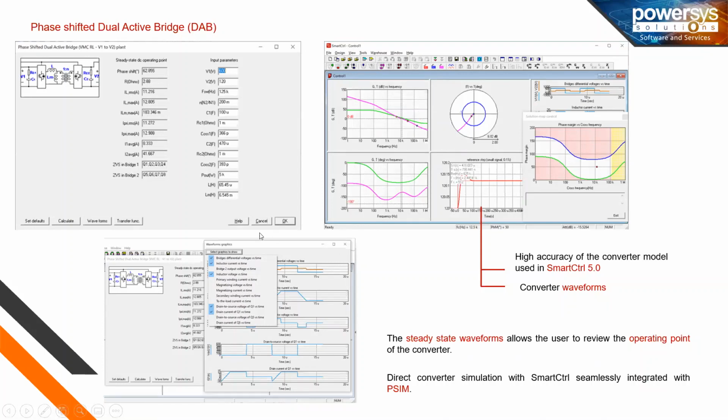As I mentioned, we have added different graphs to show to the user. The different switching output capacitance, like Coss for ZVS, has also been added in this latest version. We can optimize the control loop with the best possible bandwidth, and these calculations can be added here with high accuracy. It is already included with the transformer magnetizing inductance also. With all these things, we can provide the steady state waveforms to review operating point conditions. All this information we have provided to the user.